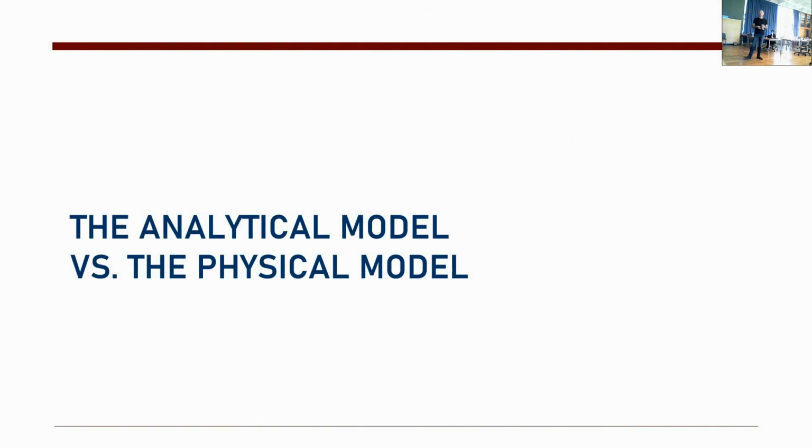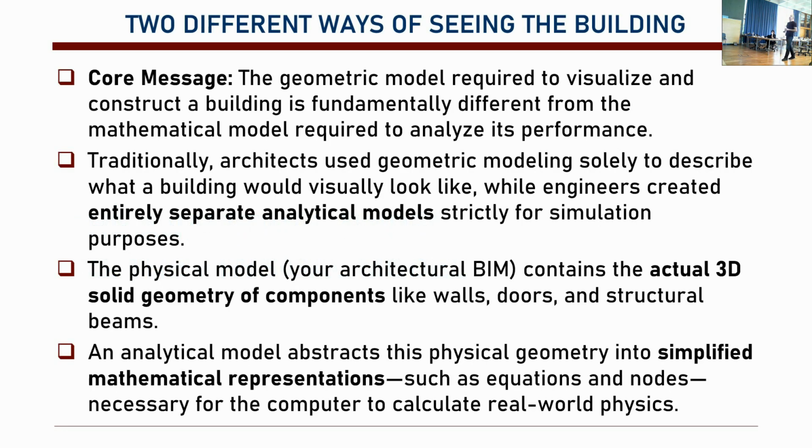Then we have this concept of the analytical model. Let's talk about that a little bit. The geometric model is, as you did with modeling in Revit, the actual representation of the physical reality, right? So we have walls, windows, floors, roofs, etc. They are all representing reality geometrically. But when we are dealing with simulation, we really don't want that much information. For energy, all I want is the limits of this space and the openings. That's all I want.